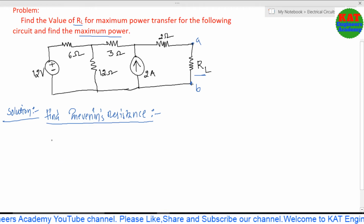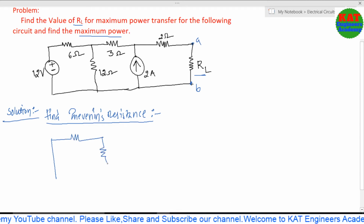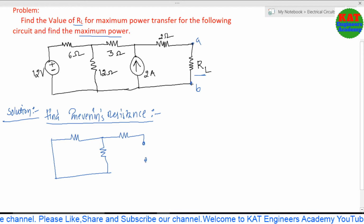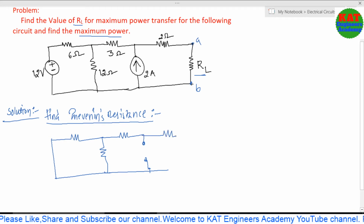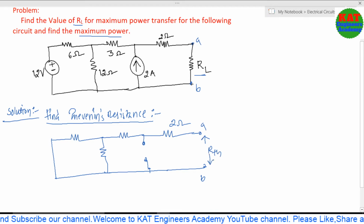So the voltage source you make a short circuit. Now here we have the 6 ohms. Next here we have the 12 ohms. Okay. Next we have the 3 ohms. Next we have the current source, which you have to open. Next we have the 2 ohms. Next, at A and B, the load resistance you have to open. Next you have to calculate the equivalent resistance, which is RTH.